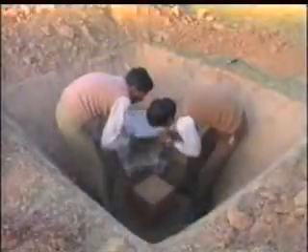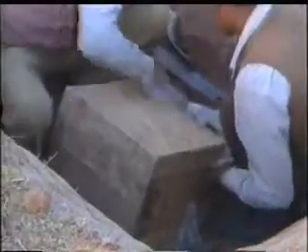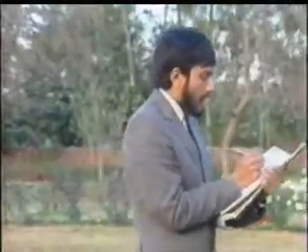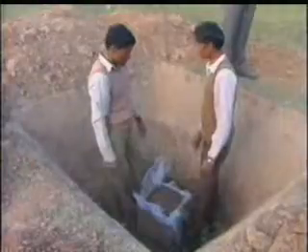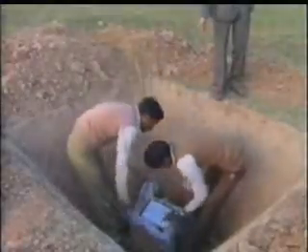A polythene sheet is spread inside the box to enclose the sample in order to avoid loss of moisture. The box is then inverted upon the sample and lifted up carefully, giving support from the bottom. The information regarding depth, place and date etc. is placed along with the sample. It is then transported to the laboratory.